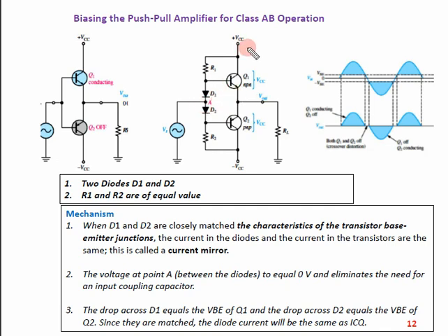Now if they are complementing each other, the value of plus VCC, R1 and D1 is such that it produces a voltage at A, let's suppose x volts. Now by symmetry, this Q2 is complementary to the NPN, R3 is similar to R1, and D2 is similar to D1. So this arrangement is going to produce a voltage at point A equal to minus x volts. So this was x volts, and this is minus x volts.